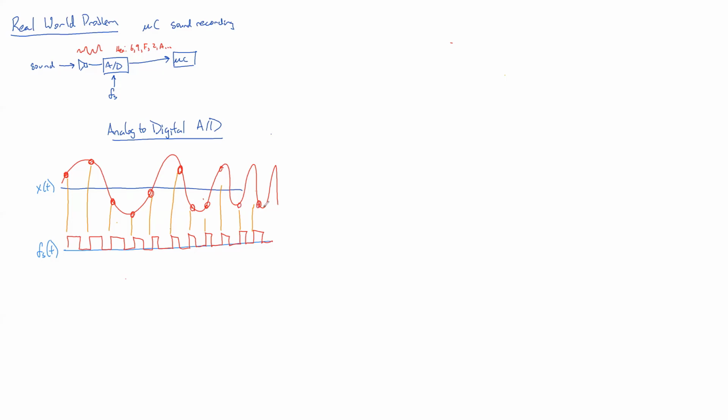So from this, it's pretty clear that the low frequency portions are modeled well. If you were to reconstruct this, you get a pretty good representation of your original waveform, and so you'd hear it rather well. But as the frequency of your continuous time signal gets higher, it stops looking like what it should look like. It looks like a completely different waveform. It's even clearer if we take out that zero line. And this is a common problem in discrete time.